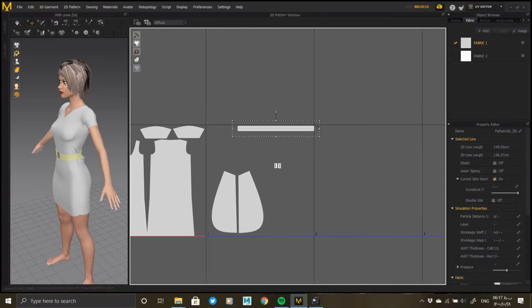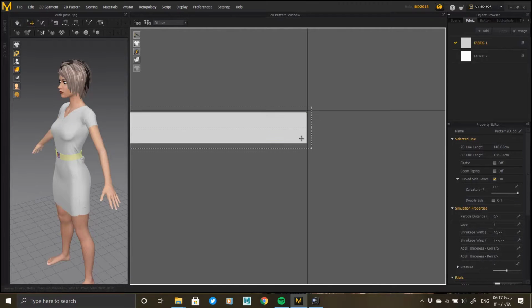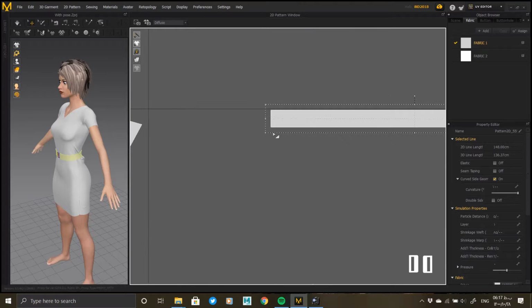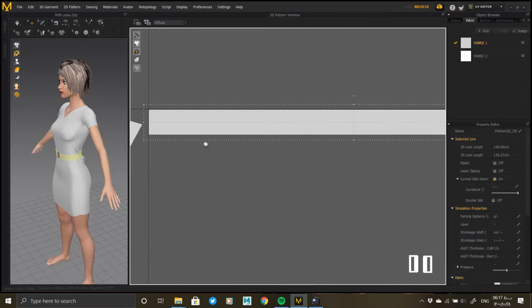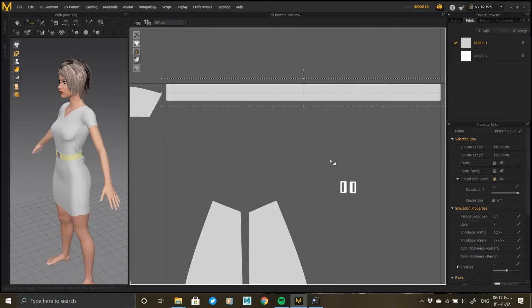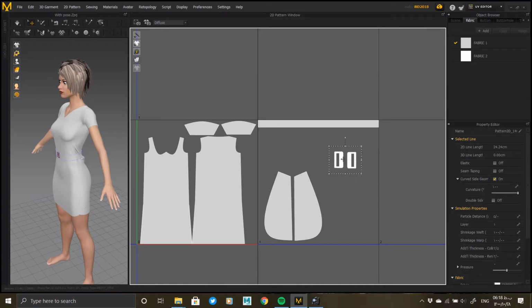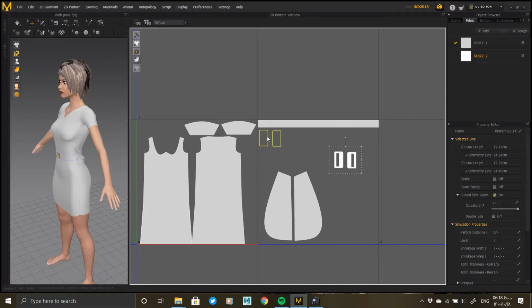When making UV, care must be taken that the clusters do not cross the UV boundary line, and that the clusters do not overlap. The next step is to prepare the model topology. The current topology of the model is triangular. The correct topology for other software is quadrilateral, and for the model to be standard, it is better to make the model topology quadrilateral.